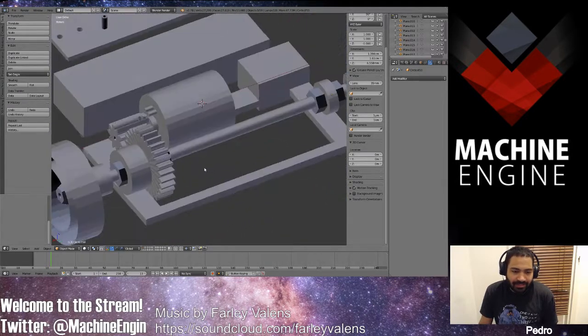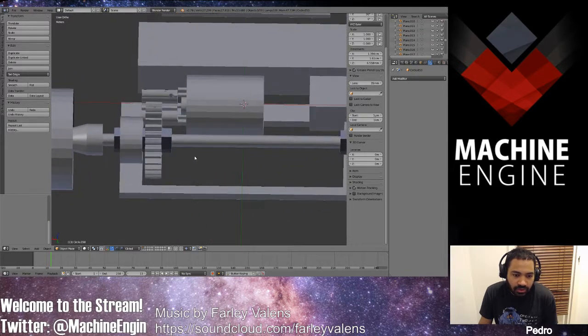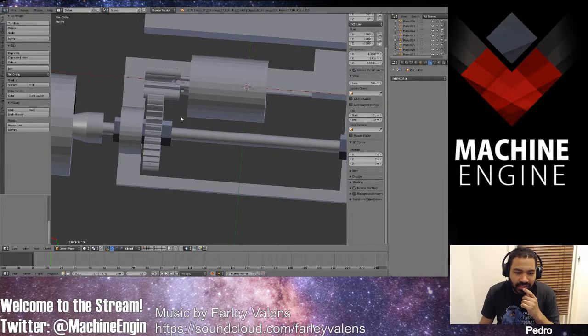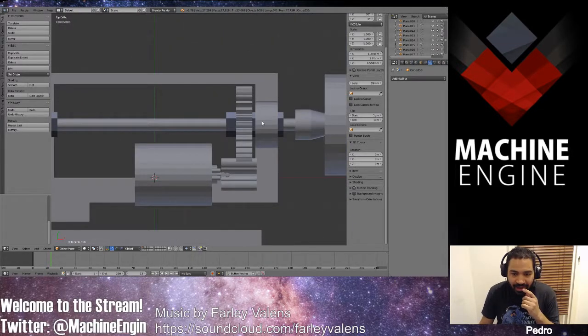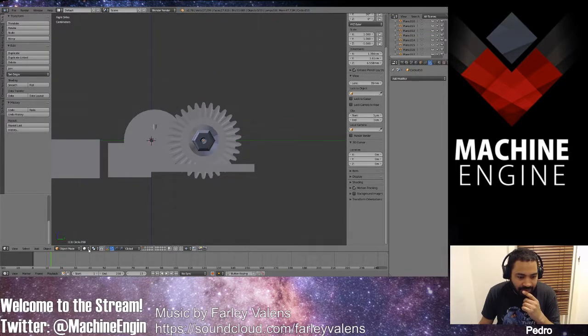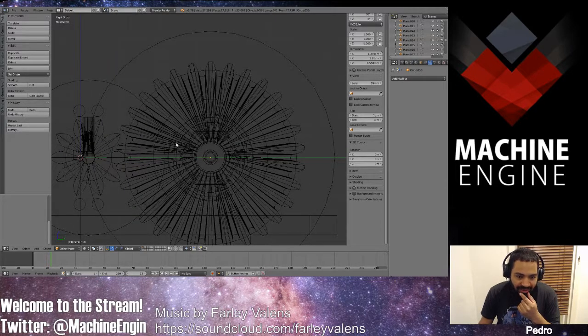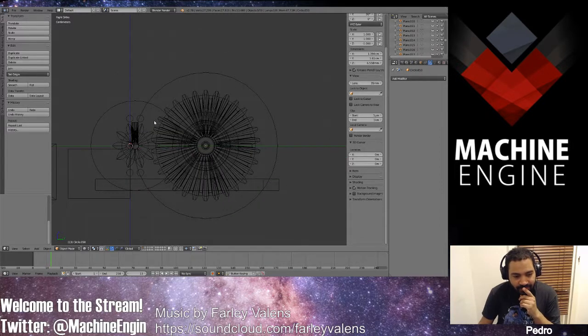So yeah, this is a complicated part. Let's see. So actually, look, the motor is there. It's kind of impeding any kind of ball bearing thing I can put there. I wonder, what's it look like on the wireframe? The motor is there. The ball bearing is here. The holder for the ball bearing is there. I could hollow it out like this, just on that one side, and push the ball bearing under the motor.